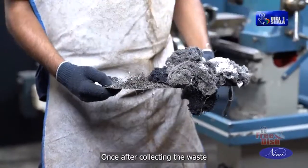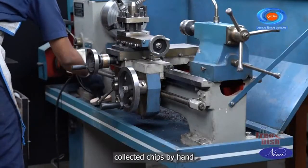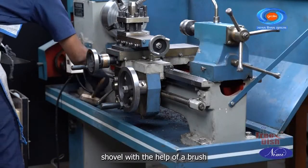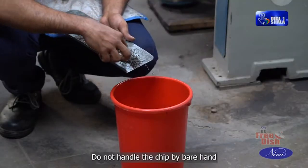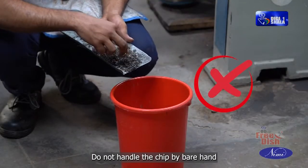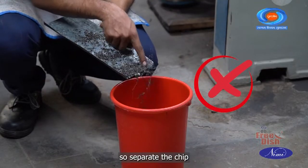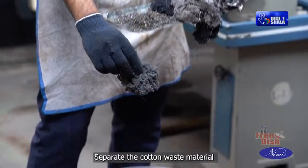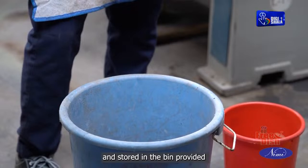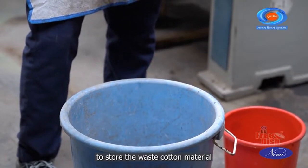Once after collecting the waste, separate the cotton waste. Collect the chips by hand shovel with help of a brush. Do not handle the chip by bare hand. There may be different metal chips, so separate the chip according to the metal. Separate the cotton waste material and store in the bin provided to store the waste cotton material.